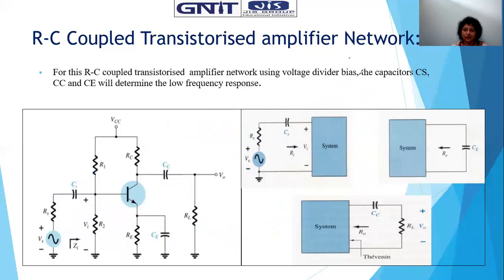We need the frequency response analysis for those series capacitors at lower frequencies, because in case of high frequency, the impedance offered by the capacitor is near zero, so it acts as a short. But in case of low frequency, AB is the highest gain, called the mid band gain, a concept already given to you. With respect to frequency, we desire 100% gain for this amplifier, but we are getting the gain in the mid frequencies only.